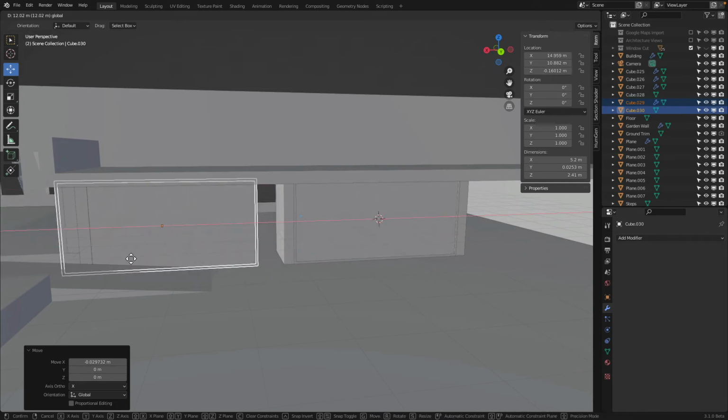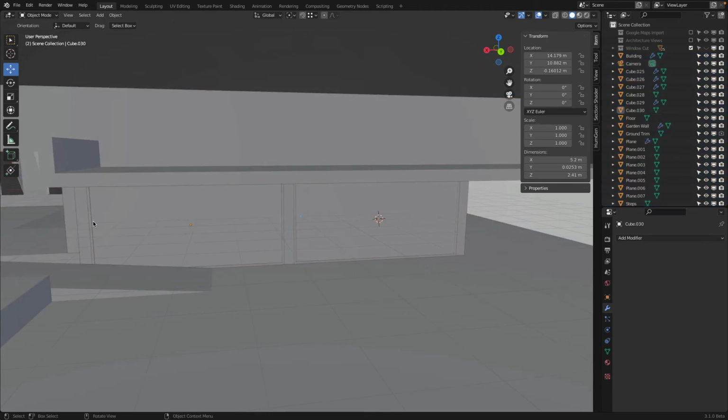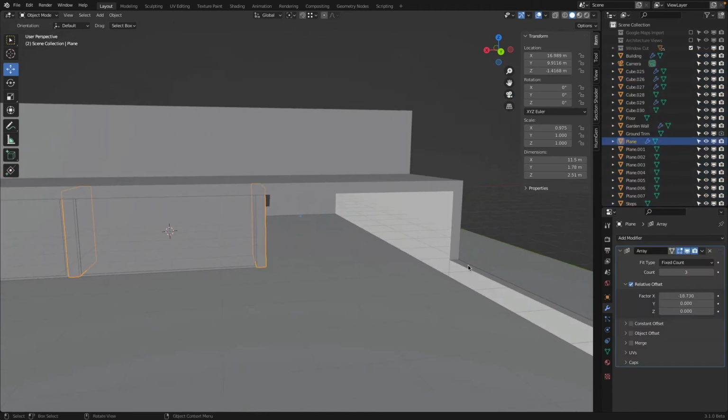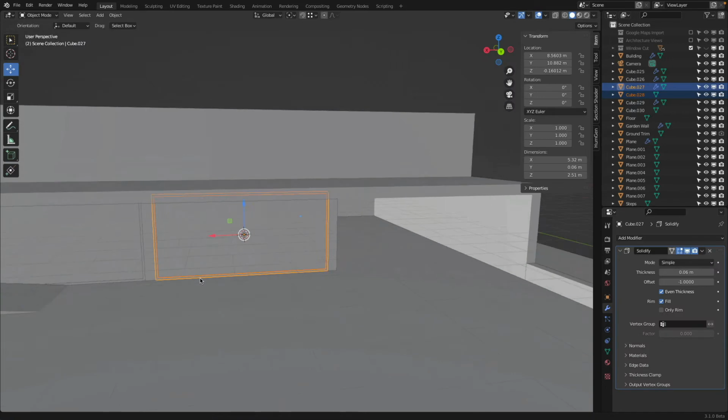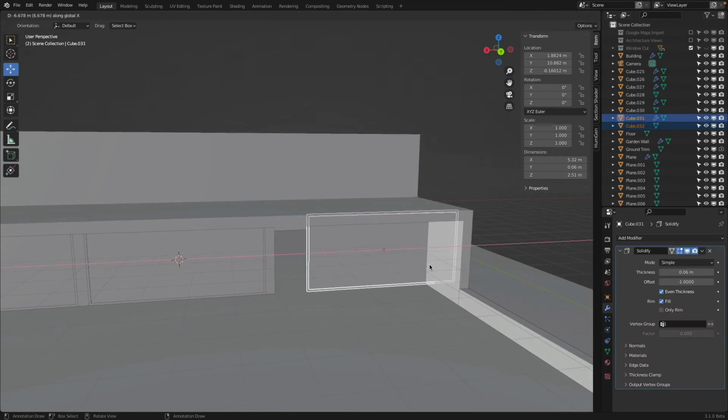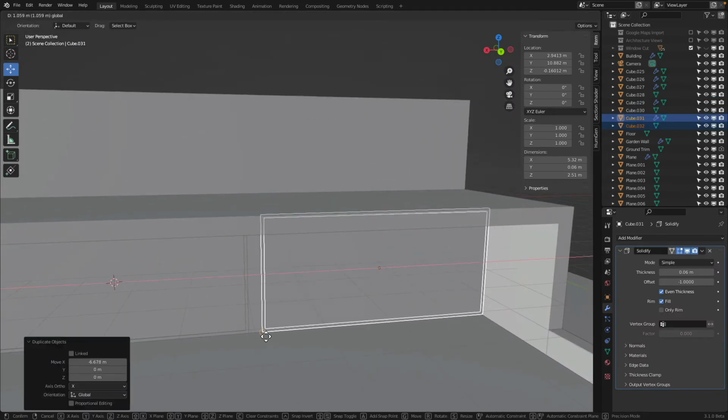Maybe it's going to be a better fit here because this is a clone. I know this base is perfect, and this, because of the modifier, this distance is not 100%. So what I will do here in this case now is Shift D and X, bring this over.